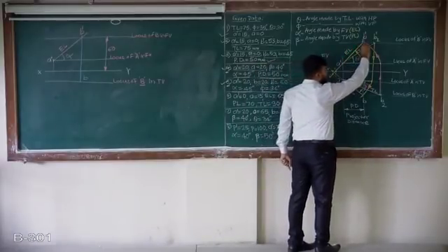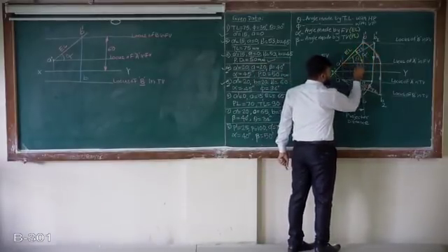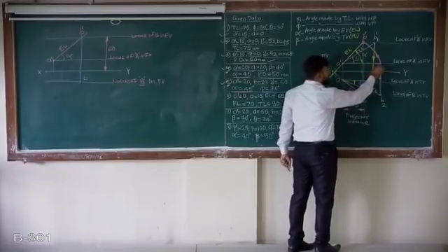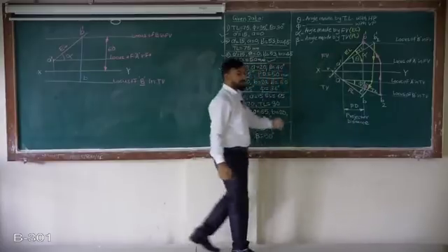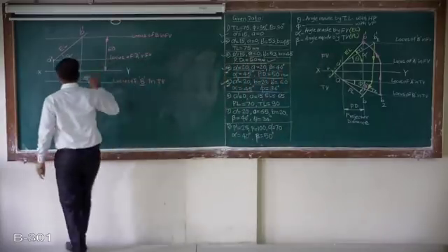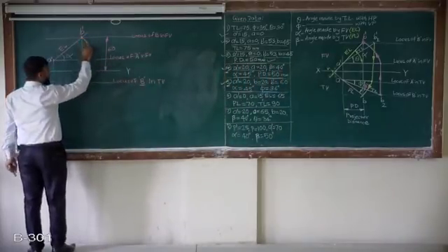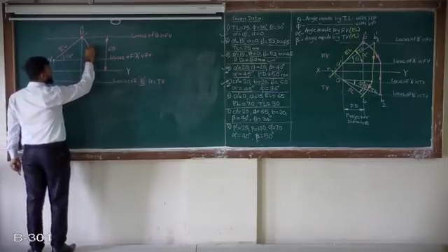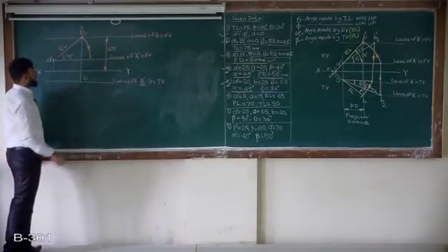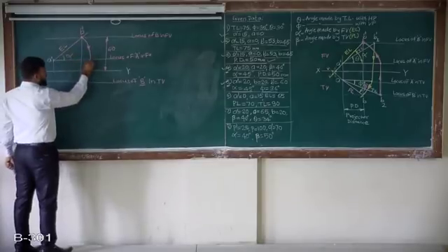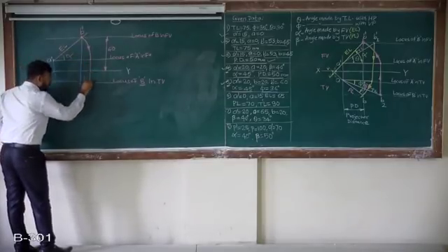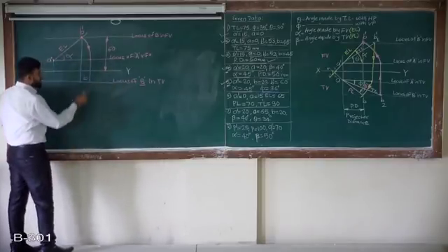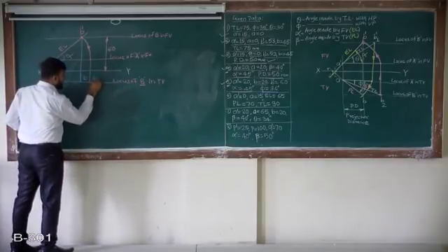See this problem. This is the elevation length. I am going to rotate this EL onto the locus of A dash and then project onto the locus of B. The same I am going to do here. Make the elevation length parallel to XY, or rotate it, and from this take a projector onto the locus of B. So that's the point B2.